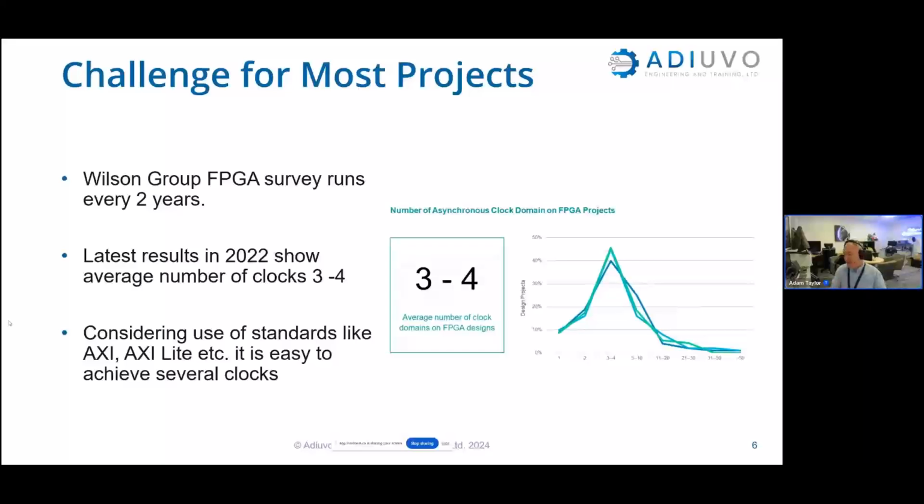So if I can ask you to bear with me, Jimmy, that's exactly what we're going to be doing in a minute. We're going to talk a little bit about what clocks are, clock domain crossing, constraints, the types of different clocks in Vivado, and then we're going to work through how we can get that baseline timing closure. That baseline timing closure is going to give you a baseline set of sensible, reasonable constraints that we can put into our design to help us achieve it. And one of the key things that I want you to take away from this is we don't just write our code and click the generate bitstream button if we want to get this done properly. So there's going to be several stages as we work through it.